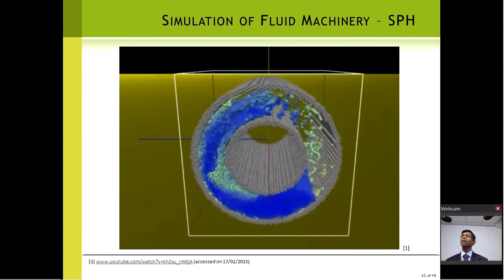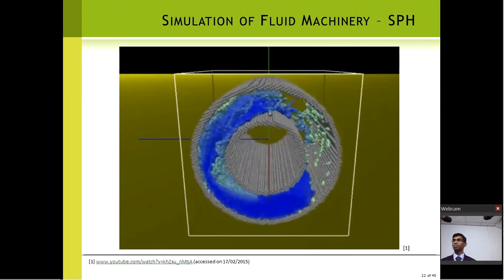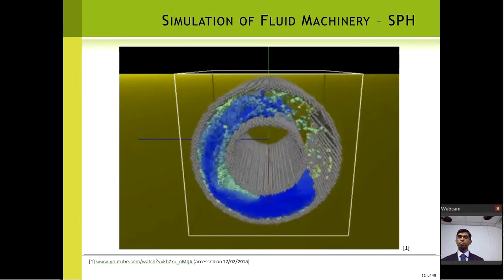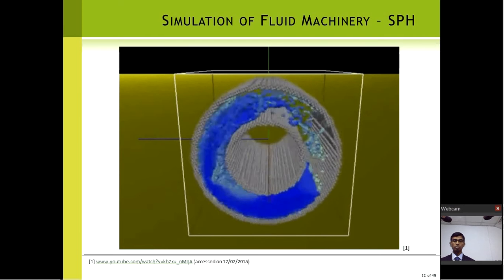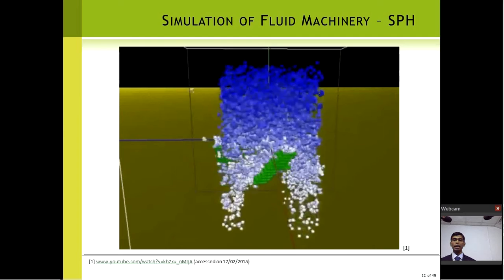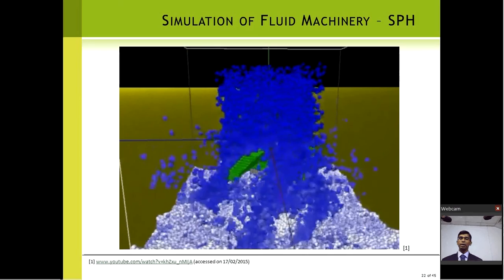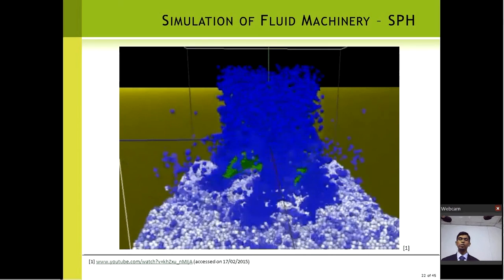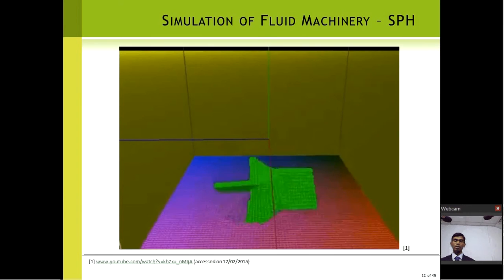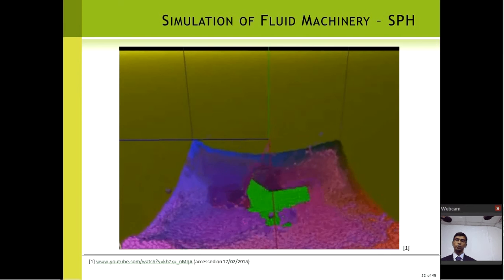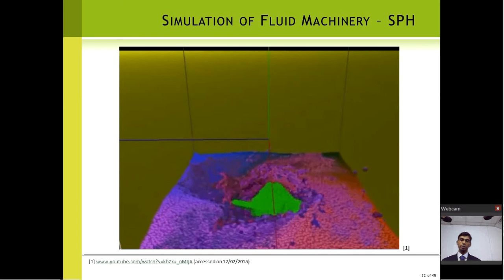Generally, the Meshfree methods are computationally costly compared to the finite element method, because in each time step we calculate what the neighbors are. That is the cost. But if we are really interested in a particular problem, we can invest in the computational cost. You can see how the mixing is going. Actually, these are basic turbines, but still you can think about the potential applications. We can physically see how the fluid will behave, not just vectors. So these are basic research. They have not been much used in an industrial context up to now, but they are being developed.